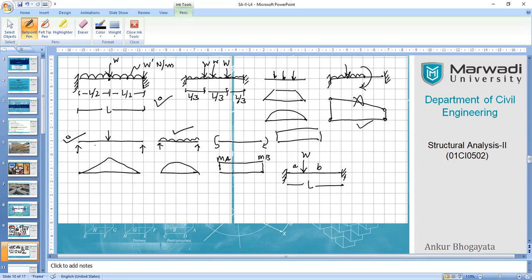According to the type of the loads, we have first obtained the simply supported beams for the individual loadings. Then the third part is only the moments applied as fixed end moments on this structure. So you can notice that we can easily draw the bending moment diagrams for all the standard cases. Later on, you can merge or club these areas together as area 1, and this becomes your area 2.